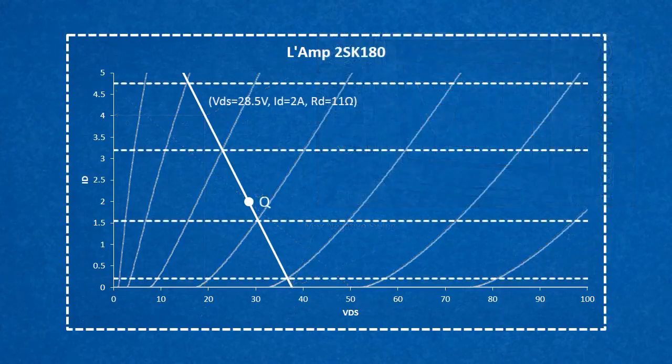Now we know about the gain and output power of our amplifier, but what about distortion? Ideally, the gain of our device will be uniform throughout the swing of the sine wave. If it isn't, our sine wave gets squished and stretched, adding new sine waves to our output occurring at multiples of the original sine frequency.